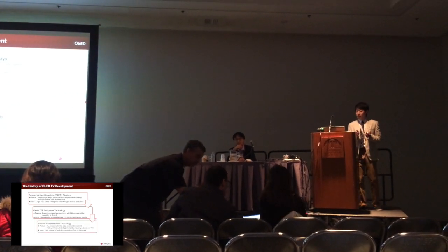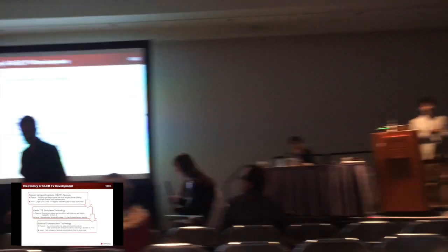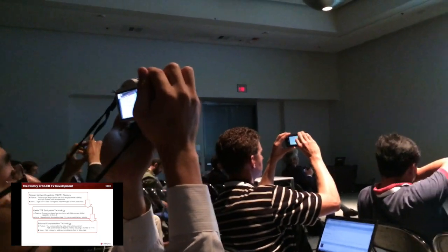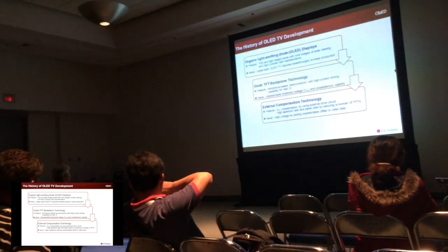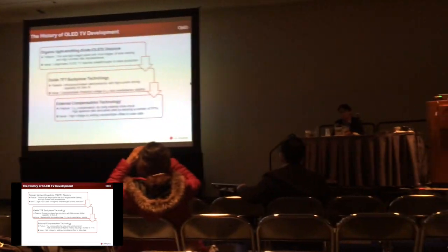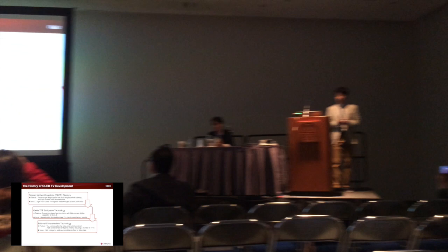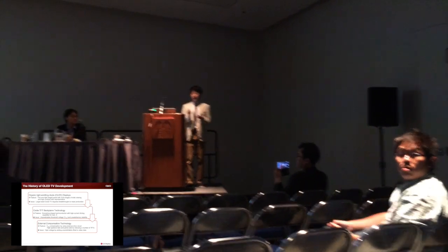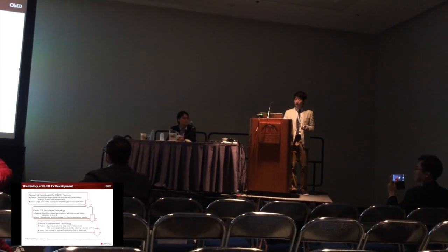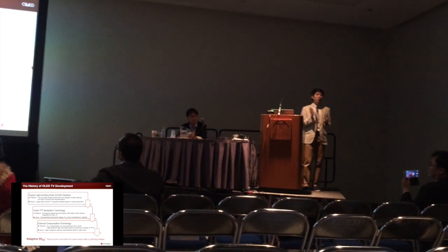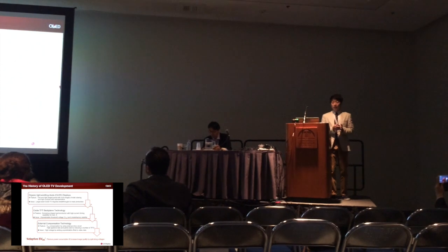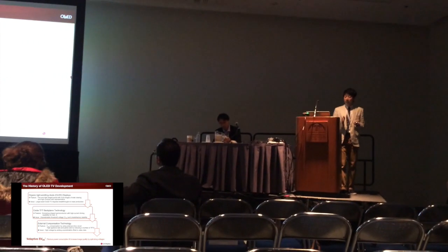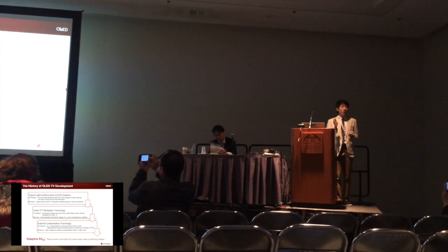External compensation technology has a strong merit to solve this problem. It can make great TFT compensation and give high aperture ratio and panel yield by reducing the number of TFTs. But it uses high voltage by adding an unpredictable offset to video data. That's why you have to remember adaptive SVDD. This is the solution to reduce power consumption and increase image quality by optimizing voltage.